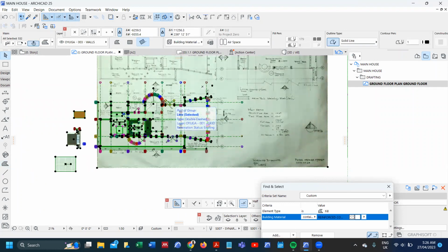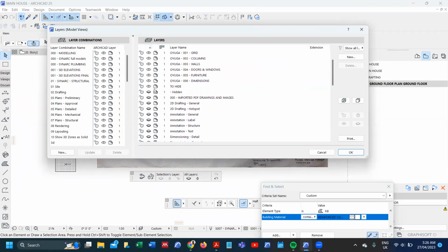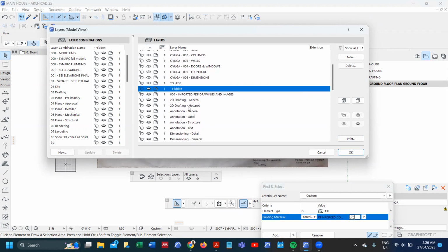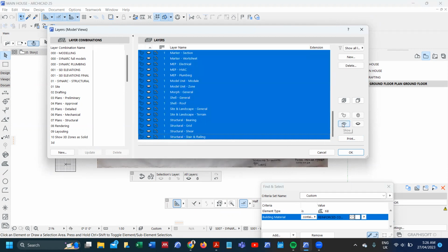After showing everything, you can decide to select everything. Okay, that ensures that you have selected all the layers that you have currently used, and then you can hide all the other layers that you're not using. Once you do that and go to the layers, you'll find the layers that you're not using. And I can comfortably do away with them, so I want to delete them instead of having them.